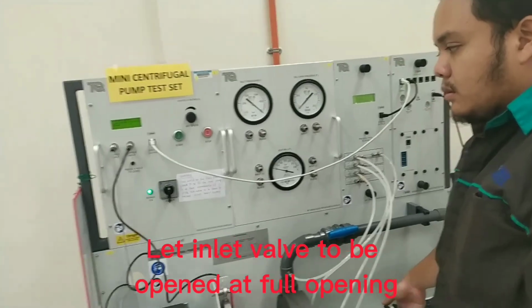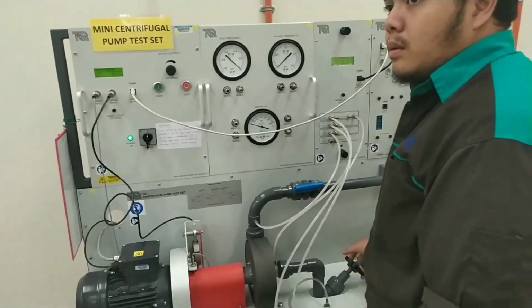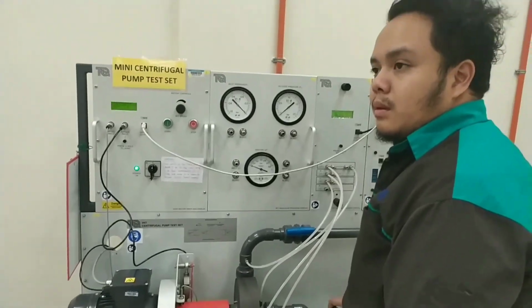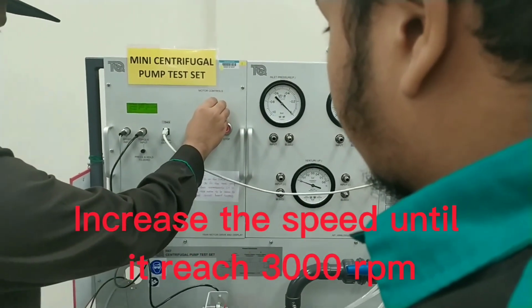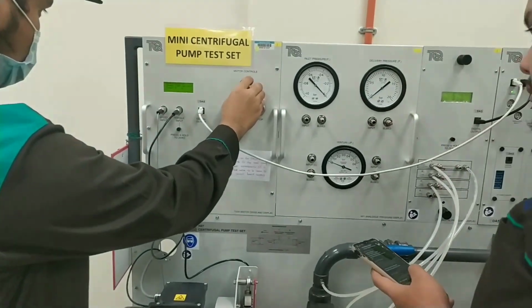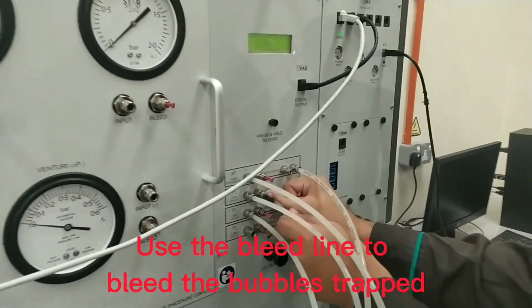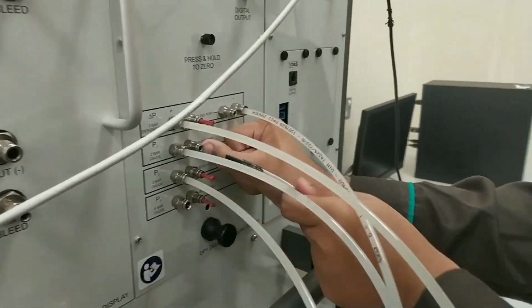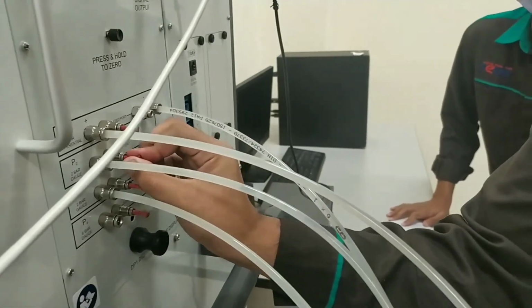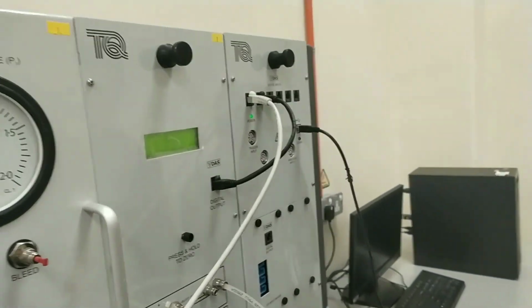Let the inlet valve be open at full opening. Increase the speed until it reaches 3000 rpm. Use the bleed line to bleed the trapped bubbles. When the system is stable, record the reading of delta P1 and P2.